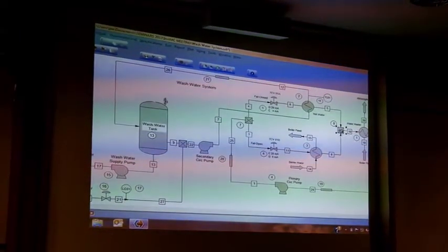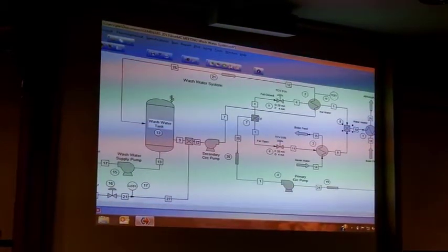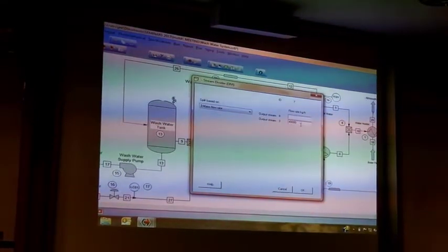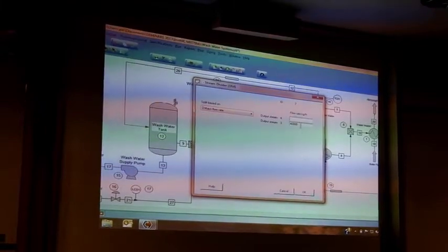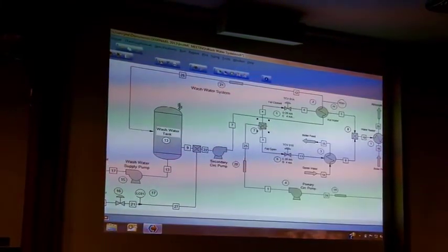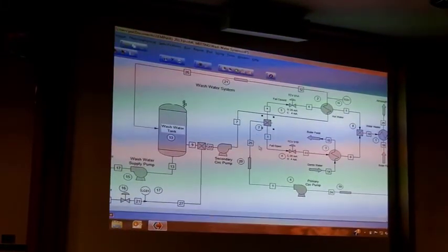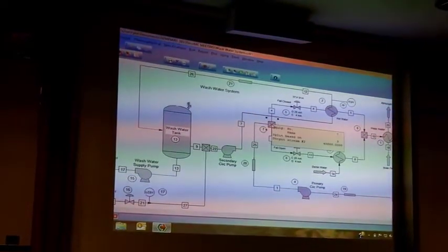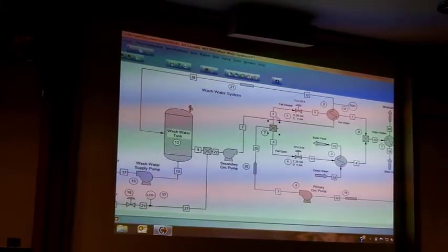This is a mixer, and that's a divider. That divider has got that value in there from the control valve, because the control valve calculates the flow in the loop. There's two control valves talking to this divider, and based on the control valve position, it tells the divider what flow to go down its leg, so they interact with each other.